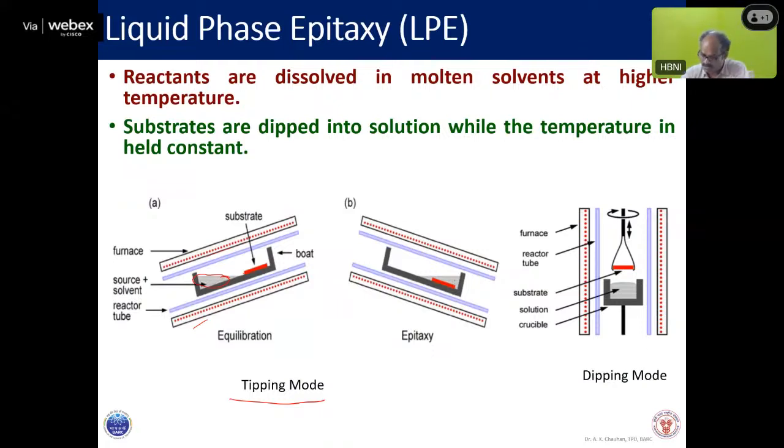And there is a dipping method, in which the source solution is placed inside a crucible, and the substrate is placed over some arrangement, and then this is brought here, and it is just touched with the solution, kept there for some time, and then slowly it is removed.